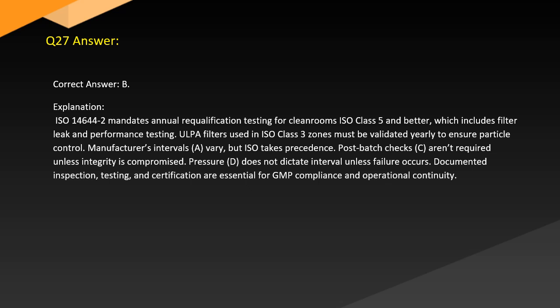Answer. Correct answer: B. Explanation. ISO 14644-2 mandates annual requalification testing for cleanrooms ISO Class 5 and better, which includes filter leak and performance testing. ULPA filters used in ISO Class 3 zones must be validated yearly to ensure particle control. Manufacturers' intervals vary, but ISO takes precedence.